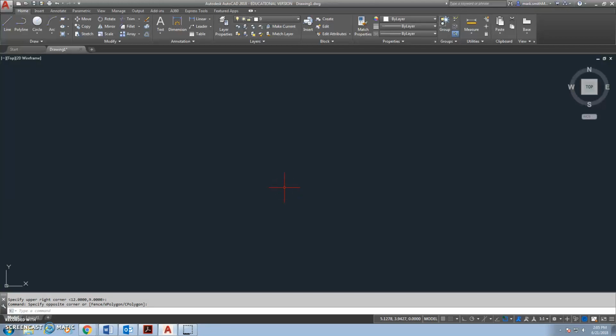In this video tutorial, we will be learning about the grid system in AutoCAD. The grid system can be accessed a number of ways. You can type grid at the command prompt, and then you get all these options. You don't quite get them all, but you get a lot of them. Okay. So if I wanted to turn the grid on, I could do it right there. If I wanted to turn it off, same thing.